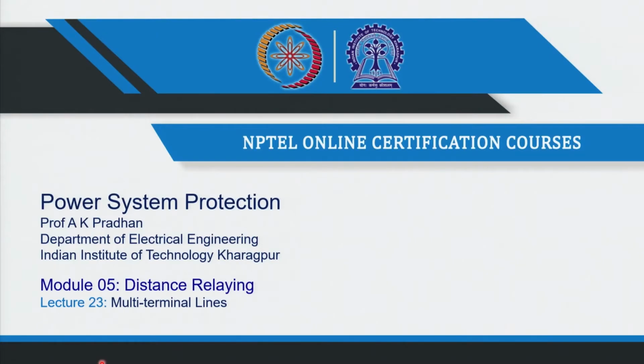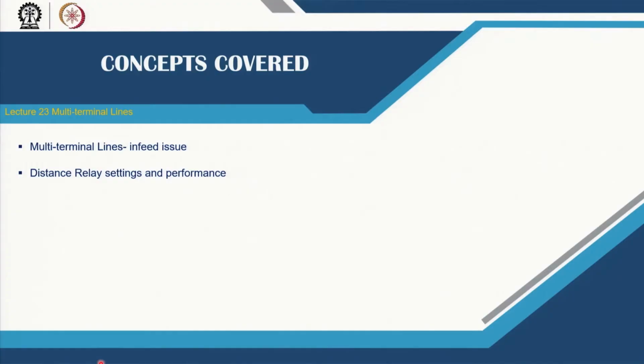Today we will continue with distance line on multi-terminal lines. This lecture is on the issues with multi-terminal lines, the protection issues, and how the distance line performs in such configurations, we will see.